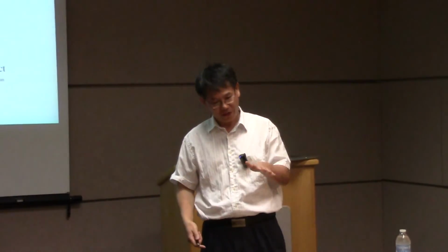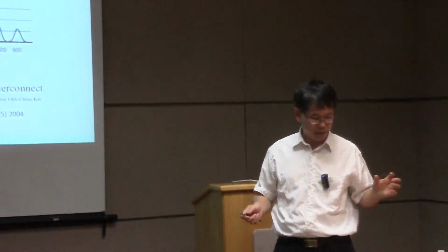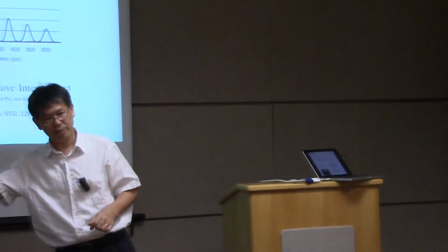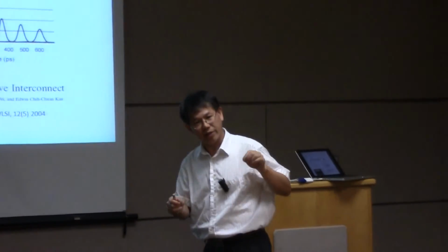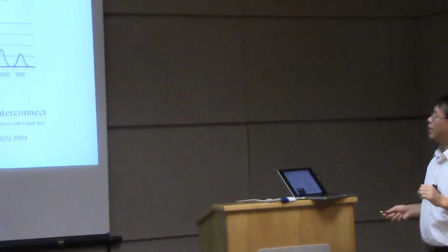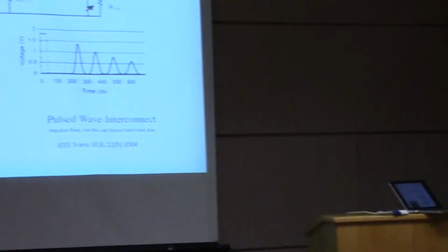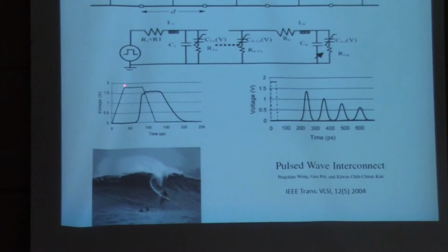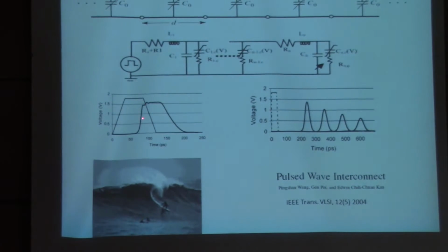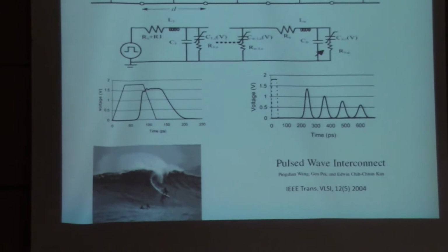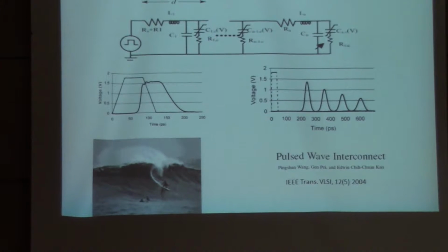nonlinear inductor there, okay? You will be able to send a pulse signal in, the pulse will propagate and keep the shape, like a bullet. It keeps the shape and does not deform. And it also can help you if you have a trapezoidal signal in, you can reshape the rise edge, or you can reshape the fall edge to manipulate your signal, okay?